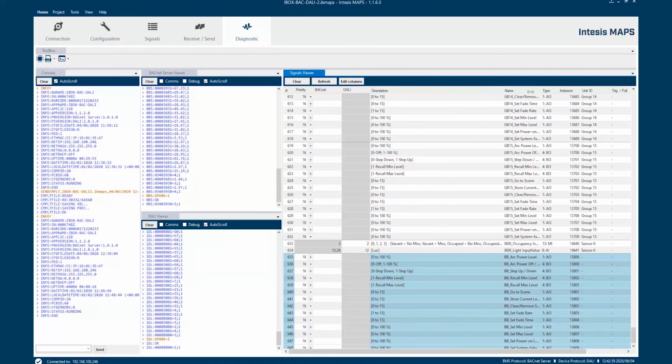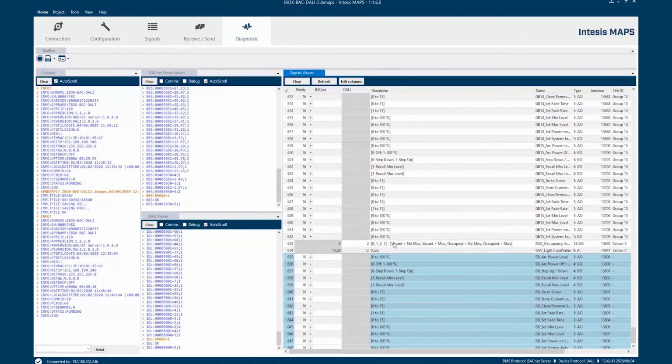the different options, the different combinations that the DALI 2 standard allows. That is when there is presence, when there is no presence. So if I keep quiet, still for a minute for the time that we have defined, this should go to 0. If I move my hand, it goes to a different level with the time that is triggered, that we have defined in the configuration.